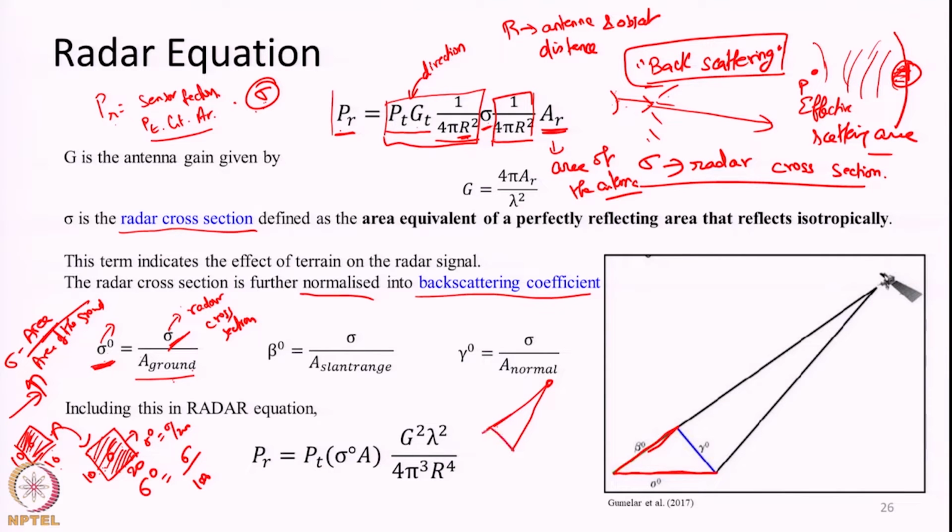In 2 dimensions it will spread and collect all the distance information and power information. Each pixel here will have an area projected in the slant range direction. If we use the area of the ground used to define the pixel in the slant range direction itself for normalizing the radar cross section, we call it beta naught.